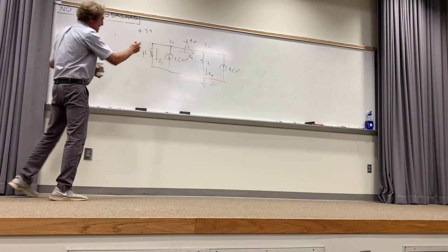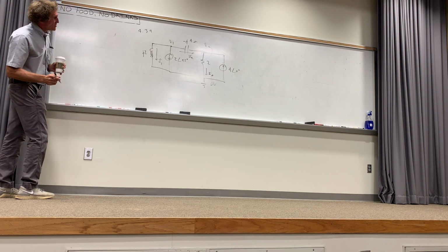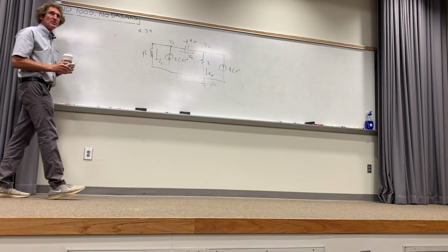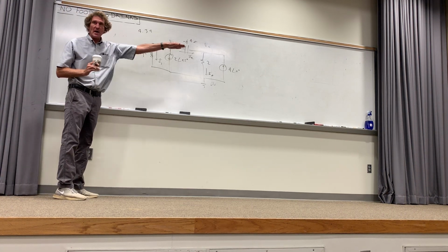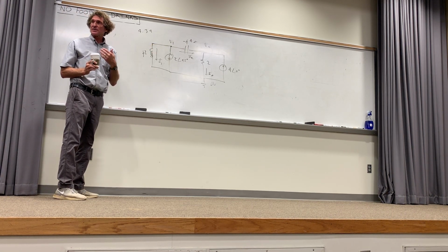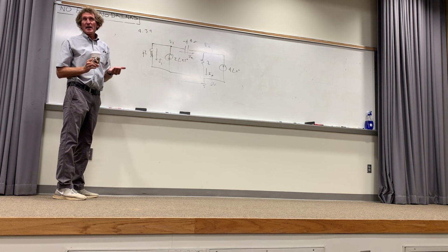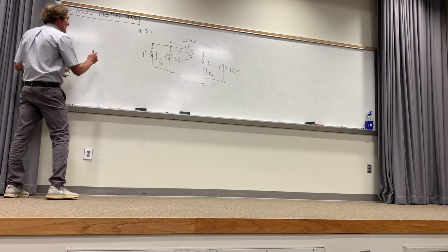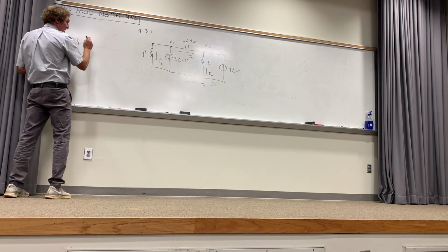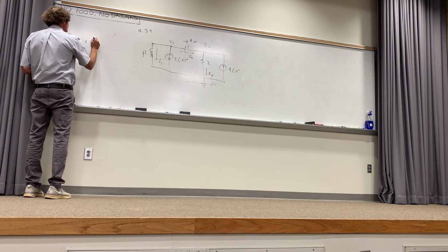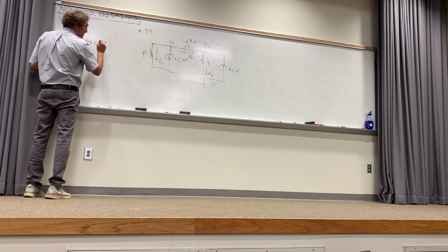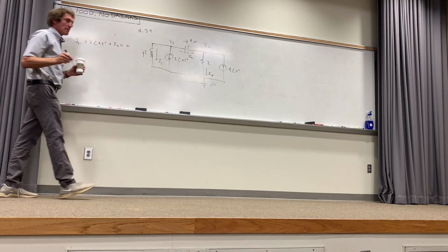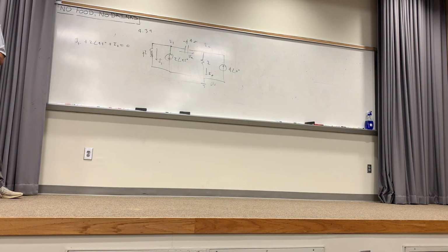So for my first node right there, when I write the equations, you'll notice that nothing's flowing in. Can y'all see that? And my convention is always going from top to bottom, from left to right, as far as the direction of currents. That's a standard I use. If you stick with that, you tend to be less likely to make mistakes. So with that in mind, I have I1, right, plus 2 at an angle of 45 degrees, plus I2 equal to 0. Y'all give me that? All right, class?